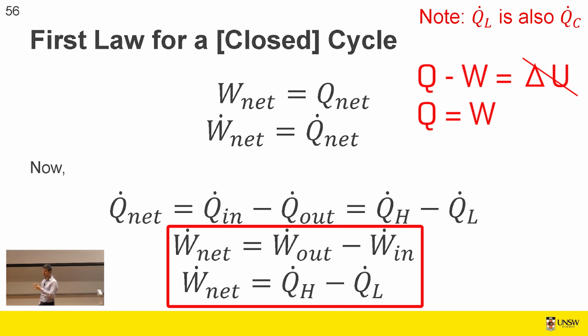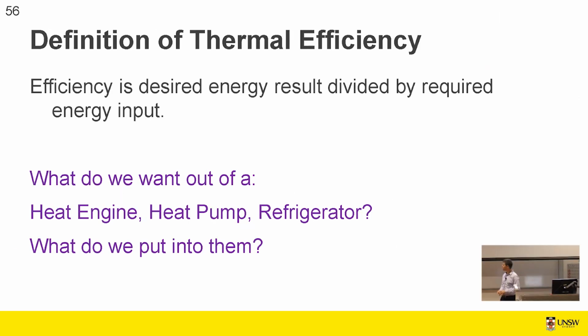And you know, there are some complicated equations relating to work, for an isentropic and an isothermal process and so forth. You don't need those if you know the heat in and the heat out. So you don't need to do crazy integrals to work out what your net work is. You just say, well, how much heat am I putting into the system? How much heat am I taking out? The rest must be coming out as work. So that can simplify our solutions somewhat.